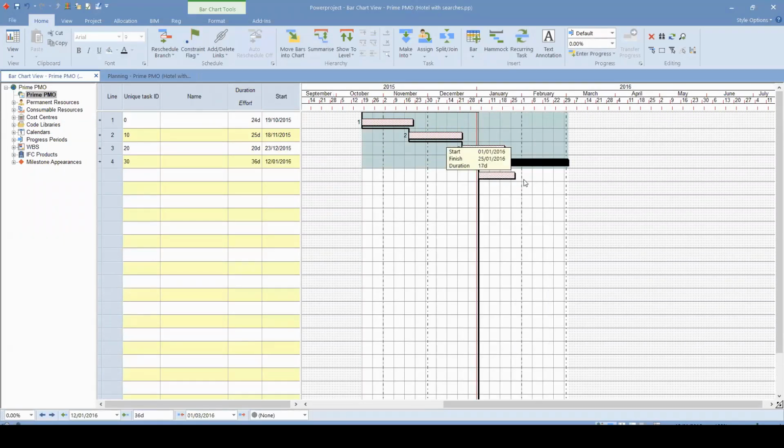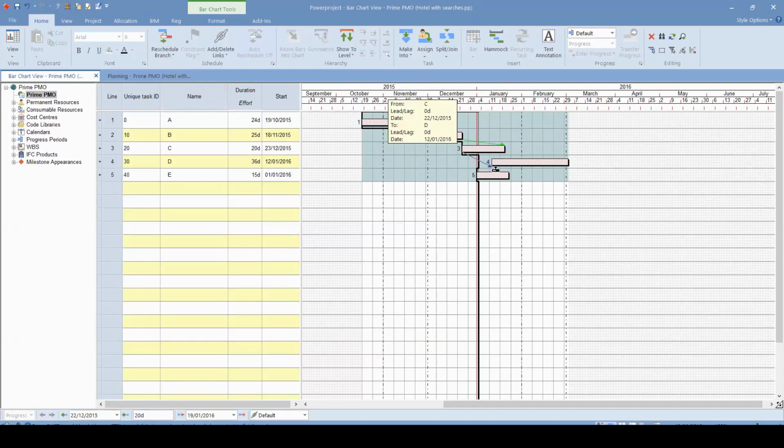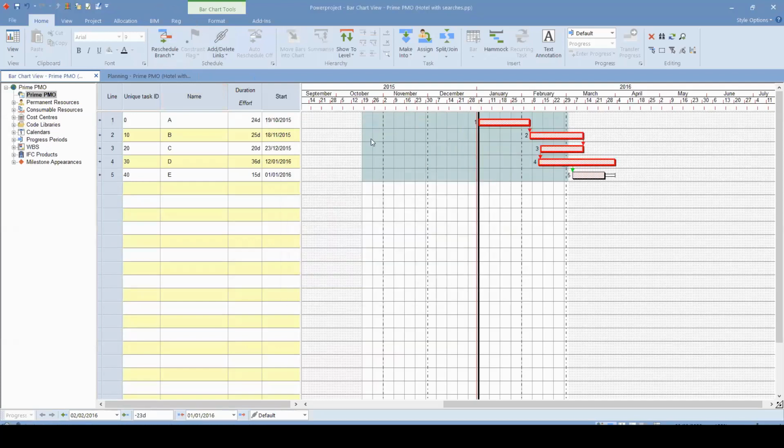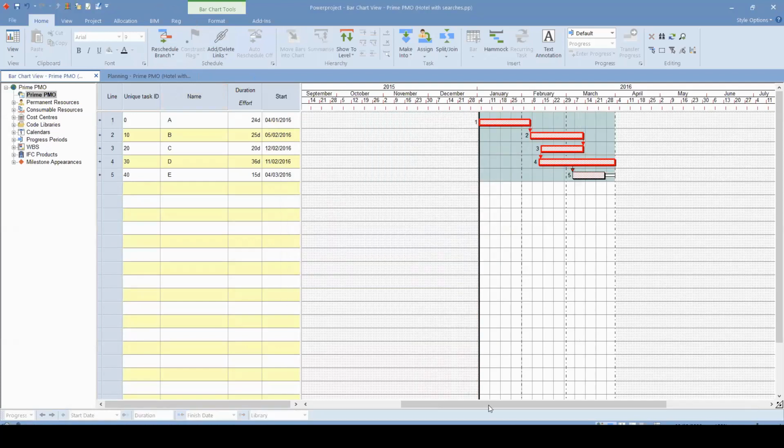You see that I'm determining the duration. Of course, anytime I can change it to 15 days, for instance. I can name the activities similar to any other software, and also draw finish to start, finish to finish, start to start, or even any start with lagged activity. Once we hit the reschedule button, the Powerproject will create